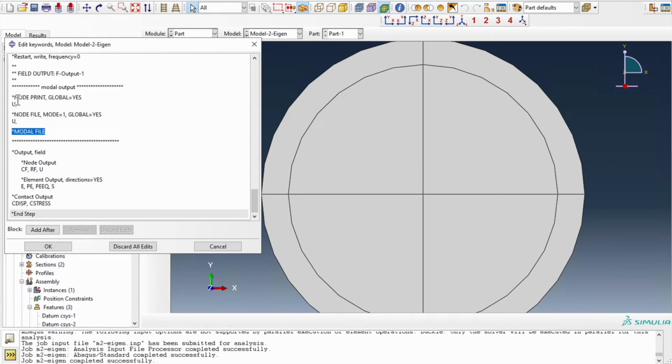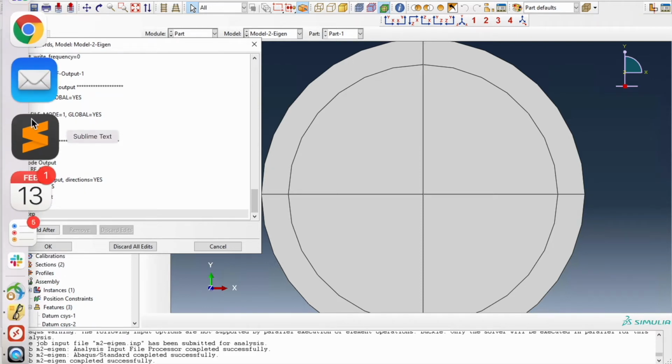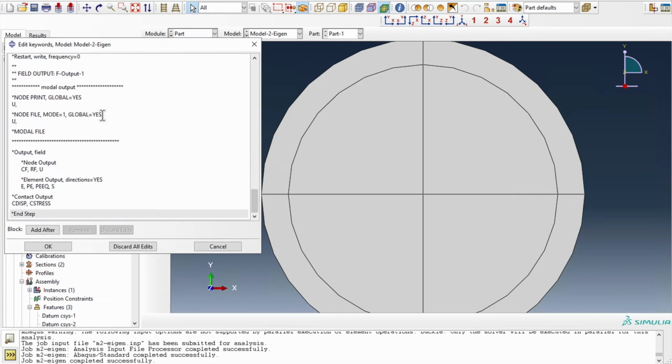This is the comment note print, where I like to print the displacement and star model file. These few lines will write the Abaqus model information, like the eigenvectors or the deformed shape of the structure in different modes, to another file, which can be called later and used to introduce some imperfection in our structure, right?